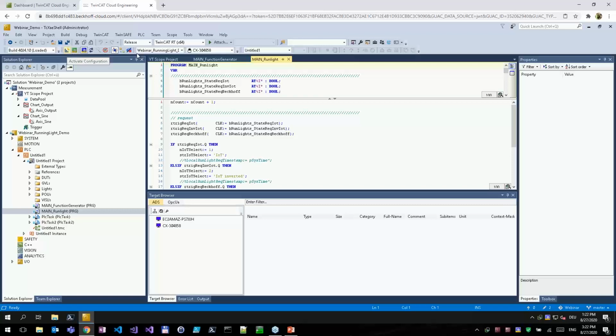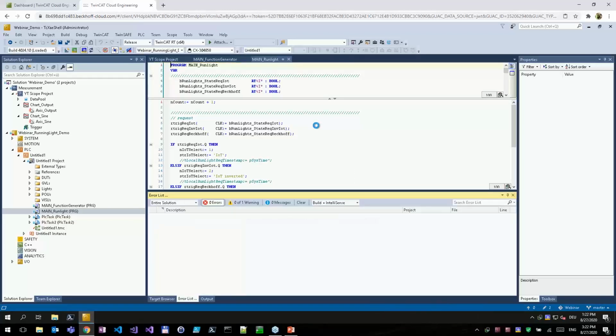So now I want to activate this project here because, yeah, I'm connected to the hardware. So I'm activating this project right now. Now it's being compiled in the background, so you know all that better than me. It's being compiled in the background for the hardware platform. And then it's asking me whether I want to restart TwinCAT in run mode now. I say yes. And now you will see that the program has been activated on the device. So I need to look for that. Yep, that looks good. So the output data is there. So the program has been activated.